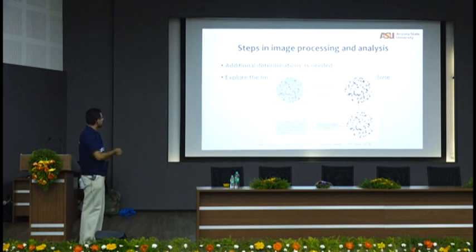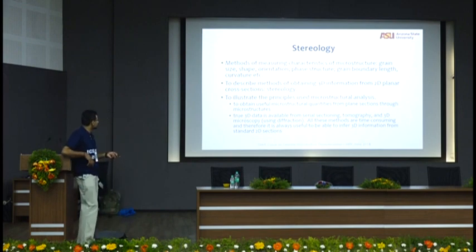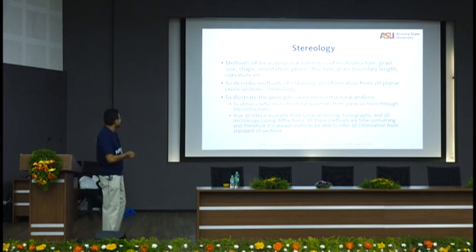Now I can do all the image analysis. So this is a pervious concrete sample. You threshold it, and your image analysis will tell you some right range of thresholding. You will get this black. You can clean it by filling, and then you can do all kinds of analysis on that. Stereology is basically you measure the different characteristics of the microstructure, getting 3D data from 2D data.